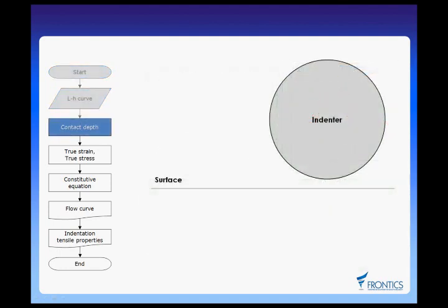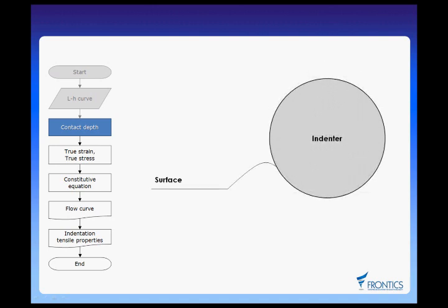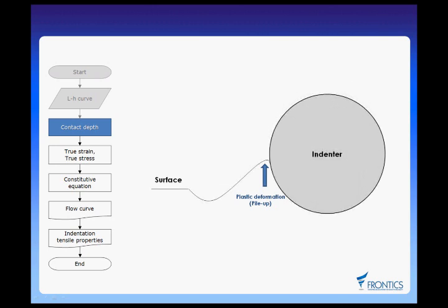Step 0 begins when we apply a load. This figure is a cross-section of the indenter when the load is applied. To evaluate material properties properly, we need to determine precise contact depth, or HC. But our equipment can only measure Hmax, or the depth from the reference plane. Therefore, to calibrate contact depth, we look at 2 factors: pile-up and elastic deflection.